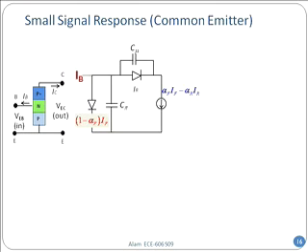Now, this is a DC equivalent circuit, or a generic equivalent circuit. I'm only interested in the small signal equivalent circuit. So therefore, I can simplify this significantly more in the following way. First of all, I drop that diode. Why do we do that? Because of course it is a reverse bias junction. Tiny amount of current is flowing, right? Base to collector, isn't it reverse bias? Tiny amount of current is flowing. That diode isn't important. I drop it. But of course, I shouldn't drop the capacitances. The capacitances are still important.